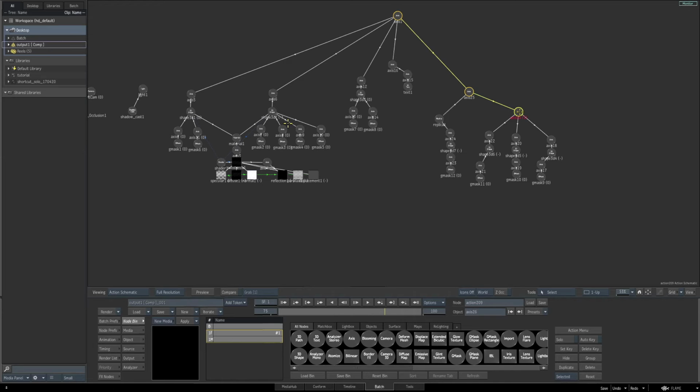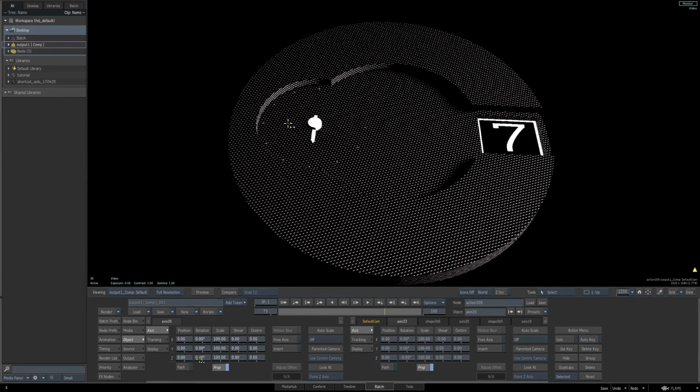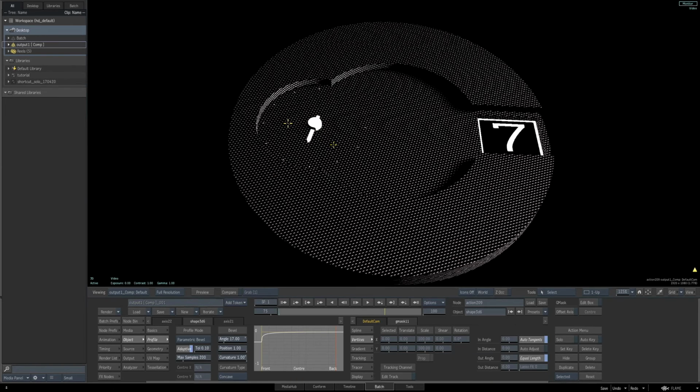So with that axis selected, the new one we just created, let's go back to our end result view, go to our object parameters. This gives us independent control of this piece of geometry compared to our indicators that we created. And now if we make a rotation to this on the Z parameter, we can animate and keyframe this to adjust as time goes by.